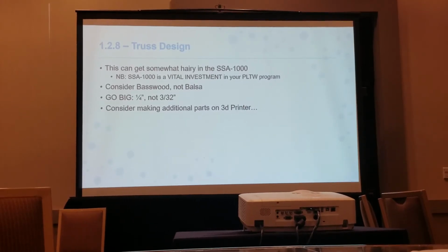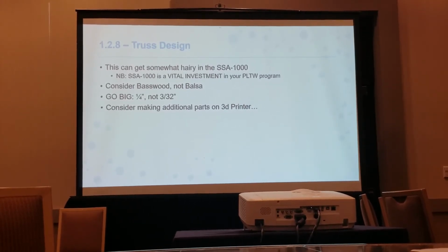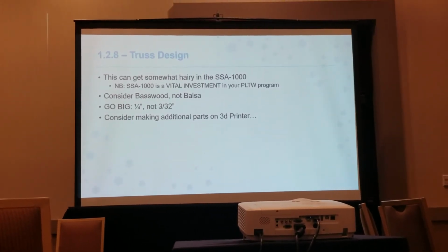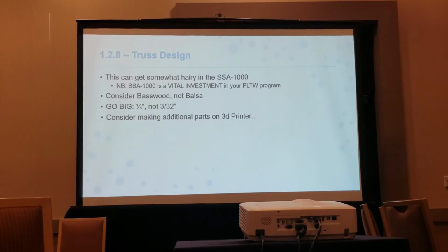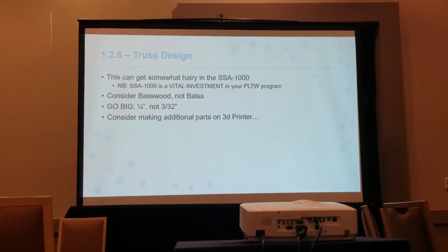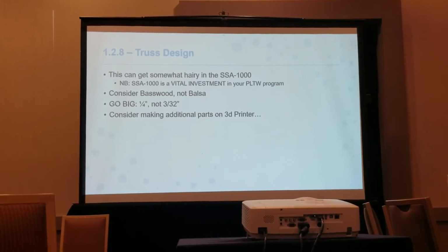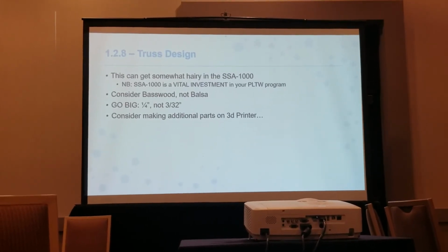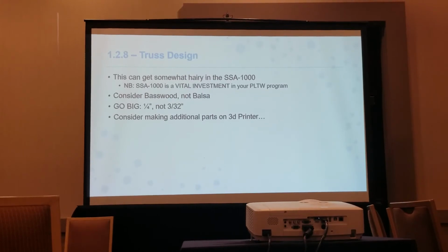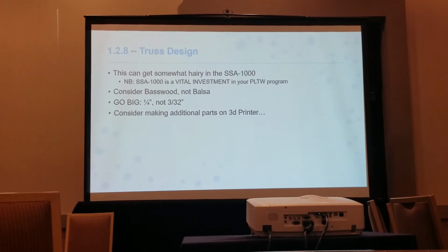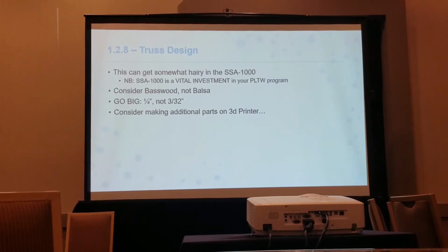But if you're using 1/8 inch balsa, you may not hit 10 pounds. And if you don't hit 10 pounds, you don't have a test. You're just assuming stuff. Whereas if you go with the bigger stuff, with the basswood, you get up into the higher stresses, the higher force loads, and you're able to actually get some comparisons between yours and yours and yours, and it's absolutely worthwhile. It's a good choice.